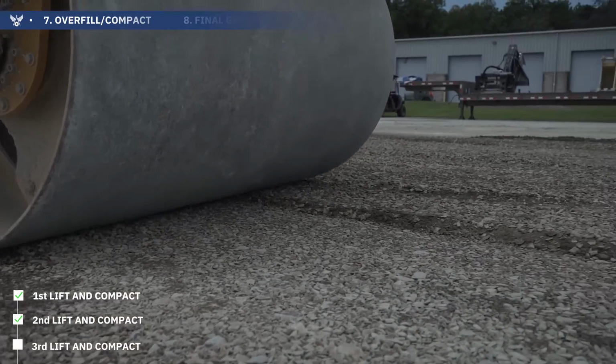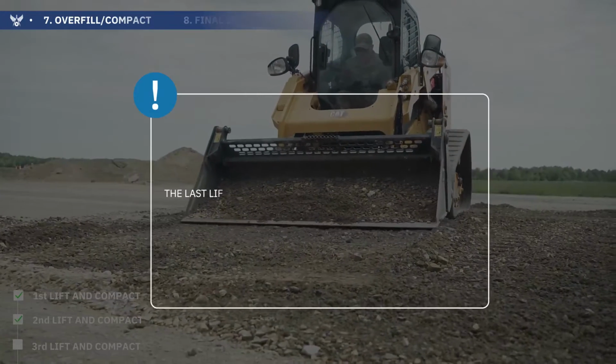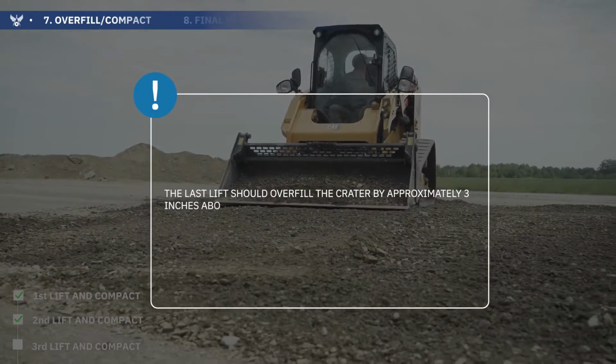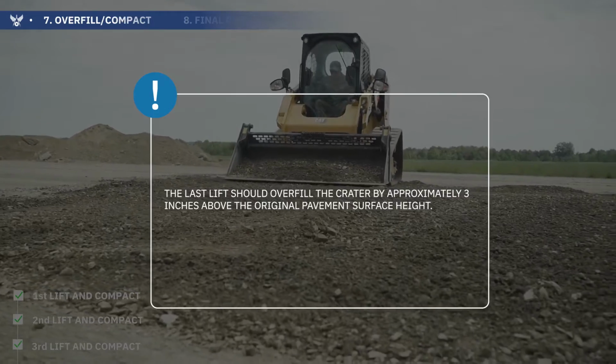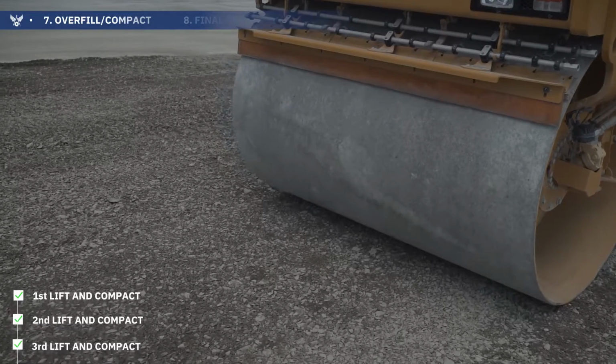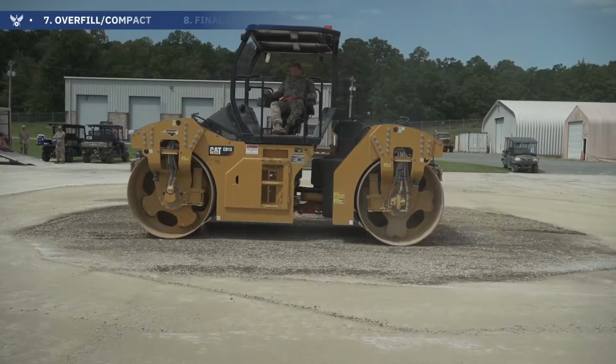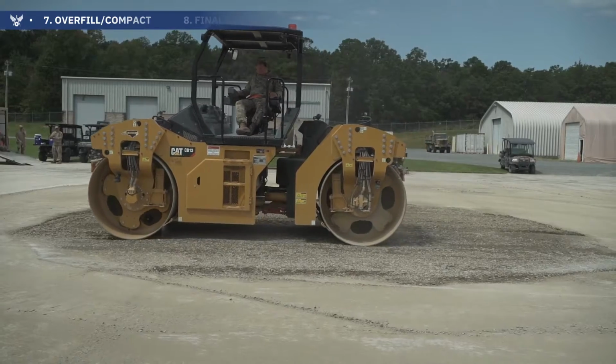Note, the last lift should overfill the crater by approximately 3 inches above the original pavement surface height. During this final process, backfill operations should be performed parallel to the center line of the airfield surface.